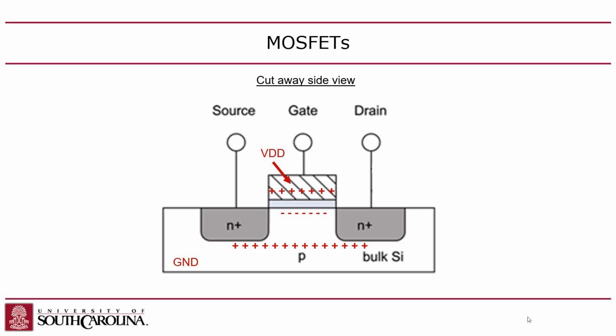So like I mentioned, the substrate is grounded. You want to ground the substrate to create a reverse bias diode. Basically, you don't want these two islands to be connected to the substrate. So you ground the substrate. But when you charge this capacitor and you create charge carriers in the channel, those charge carriers are not electrically connected to ground, to the substrate.